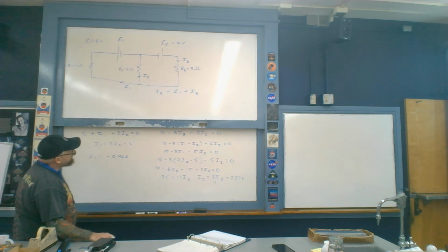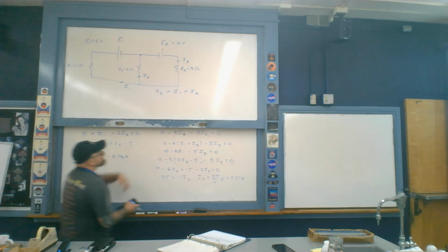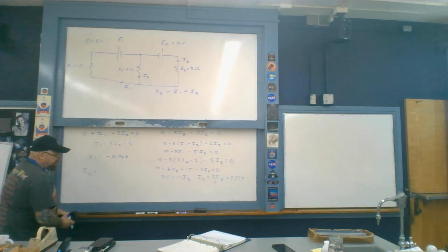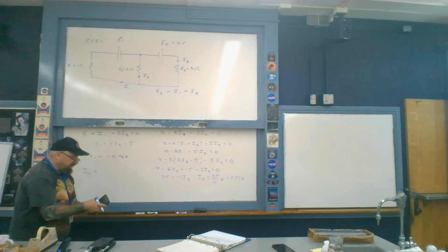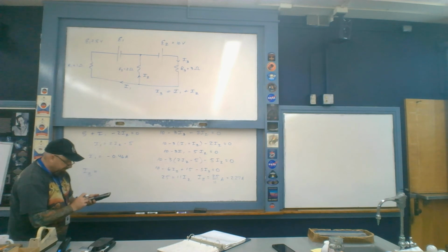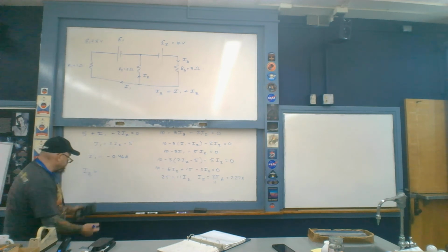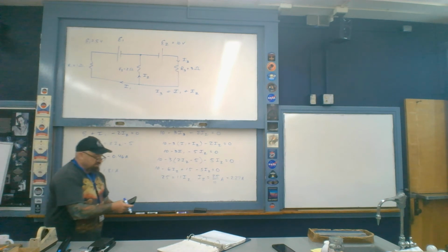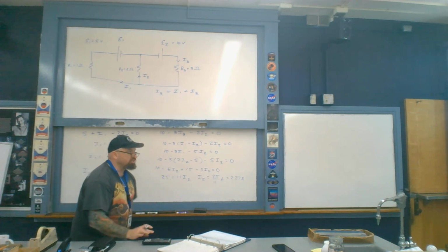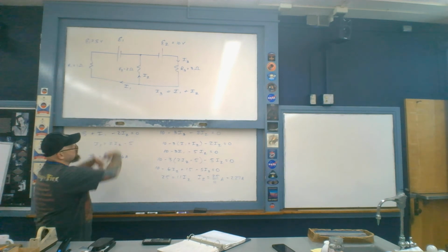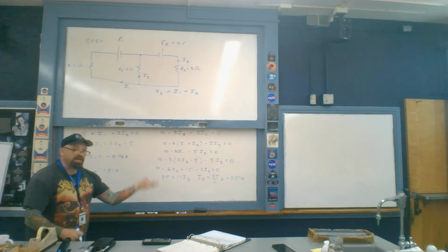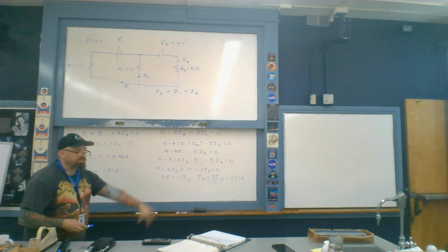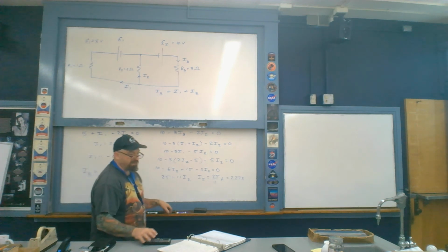Okay, let's go ahead now and find I3. That's last. We'll do so by just adding up I1 and I2. Now, when I add up I1 here, you do include the negative sign. So negative 0.46 amps plus 2.27, and that ends up being a total of 1.81 amps, like so. So basically, you just set up the 2 rules, junction rule and loop rule. You just assume directions associated with the currents and then calculate. And then whatever your answer ends up being, positive or negative, that then tells you the values and in which way the currents flow. Okay?